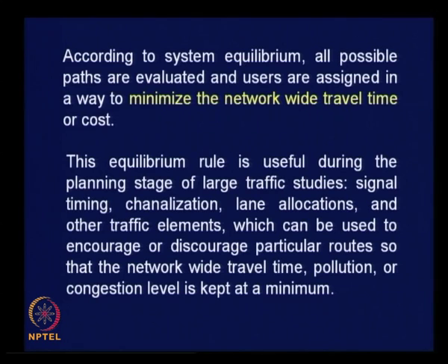This equilibrium rule is useful during the planning stage of large traffic studies, mostly not for transportation system planning, only for traffic studies involving signal timing, channelization exercises, lane allocations and other traffic elements which can be used to encourage or discourage particular routes, so that the network-wide travel time and the resulting pollution or congestion level is kept at a minimum.